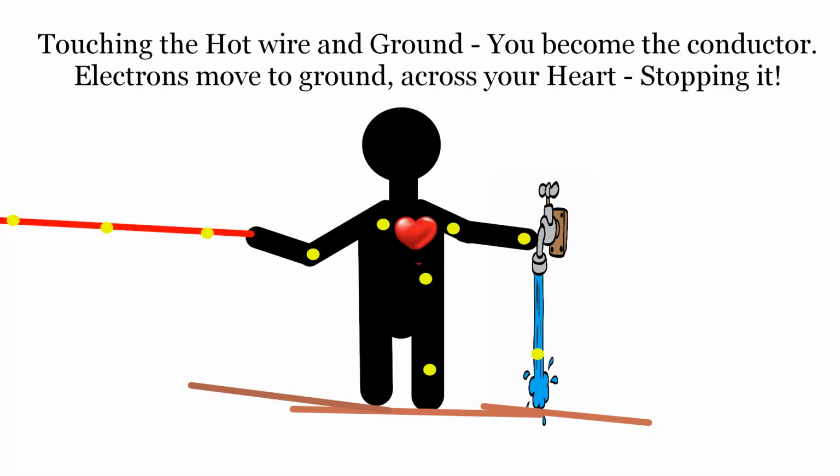In this case, through your arm and leg. It can easily stop your heart. Don't put yourself in that position. Always assume the wire is hot until proven otherwise.